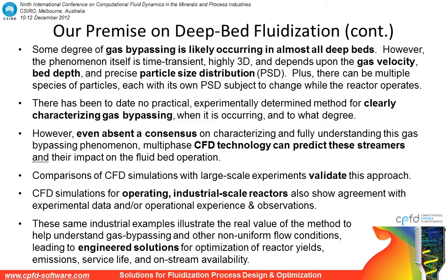However, our position is that even absent a consensus on characterizing and fully understanding this gas bypassing phenomenon, multi-phase CFD technology has been shown to predict these streamers and their impact on fluid bed operation. This morning, I'll be showing comparisons of CFD simulations with large-scale experiments that validate this approach.